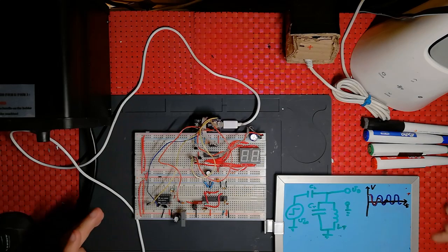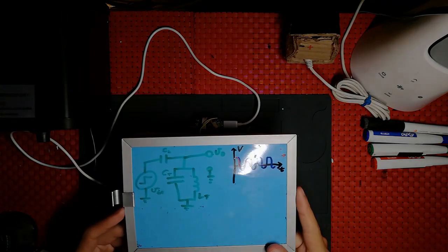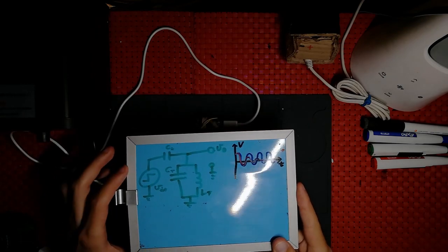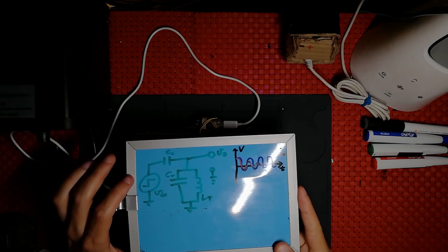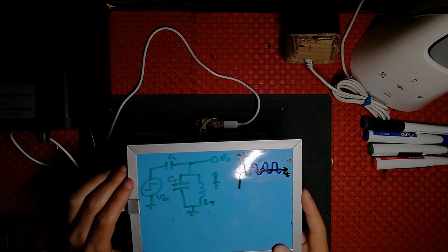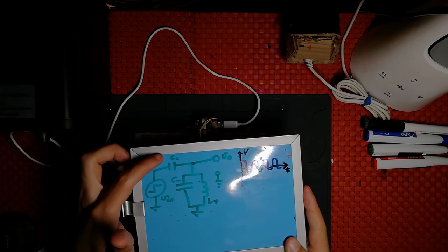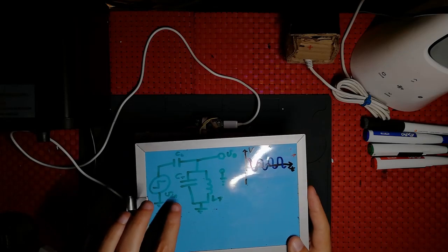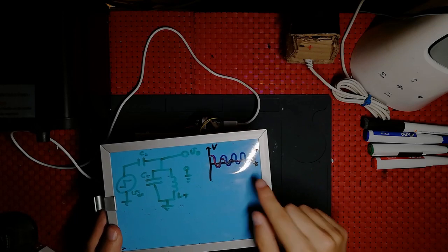So let's begin. First of all, I found out that you can use this circuit, which is called a tank circuit, I think, which if you feed it a high speed pulse, or a really low rise time or really low fall time pulse, and it goes through pretty much a DC blocking, which acts as a high pass circuitry, it will make this capacitance and this inductance ring, like it's shown here in blue.